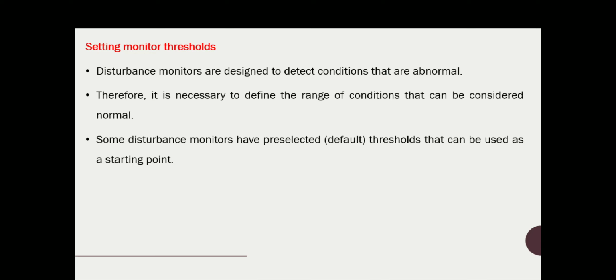The best approach for selecting a threshold is to match it with the specifications of the equipment that is affected. Otherwise, set the threshold fairly tight for a period of time and then use the collected data to select an appropriate threshold for longer duration monitoring.